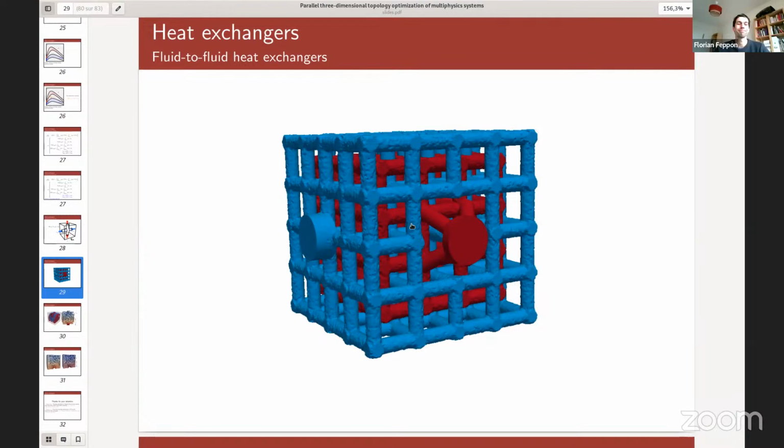Thanks. Let me add one small comment to what Florian said. He's always using the word remeshing. So indeed, it is remeshing, but not remeshing from scratch. We remesh from the previous mesh, so it takes time, but less than if you were remeshing from scratch. It just adapts the previous mesh at each iteration. Yeah, that is correct, and also the remeshing time decreases over the iterations. But the mesh topology may change, so it's really a remeshing. It's not deforming. It's remeshing, but not from scratch.